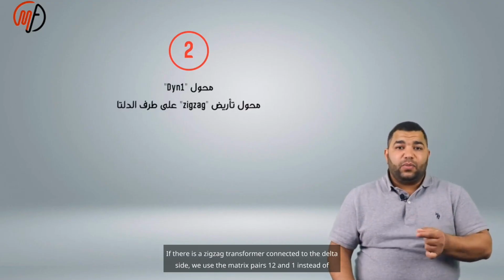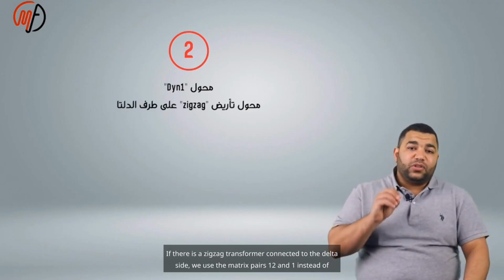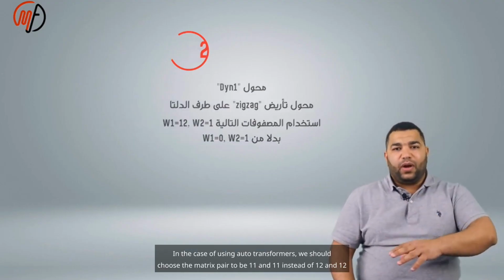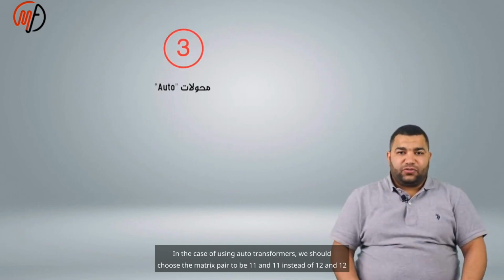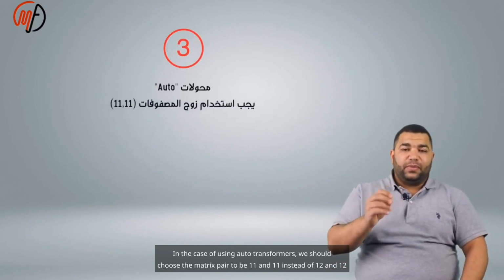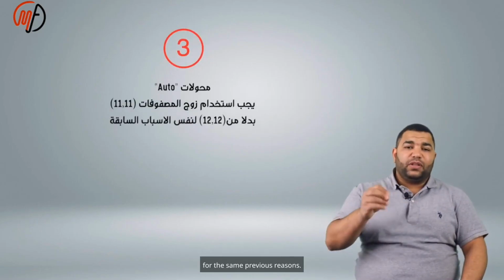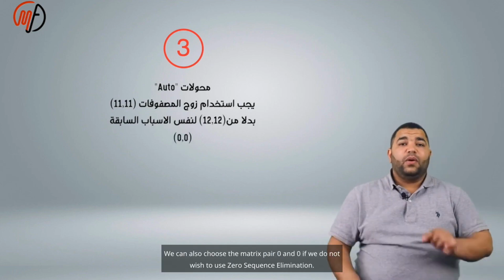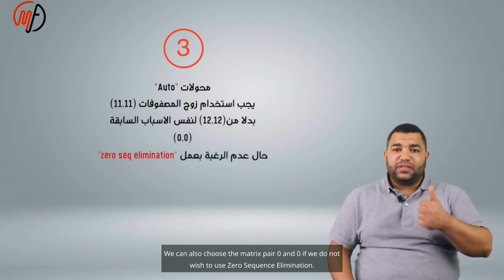As well, if there is a zigzag transformer connected to the delta side, we use the matrix pairs 12 and 1 instead of using the matrix pairs 0 and 1. In the case of using auto transformers, we should choose the matrix pair to be 11 and 11 instead of 12 and 12 for the same previous reasons. We can also choose the matrix pairs 0 and 0 if we do not wish to use zero-sequence elimination.